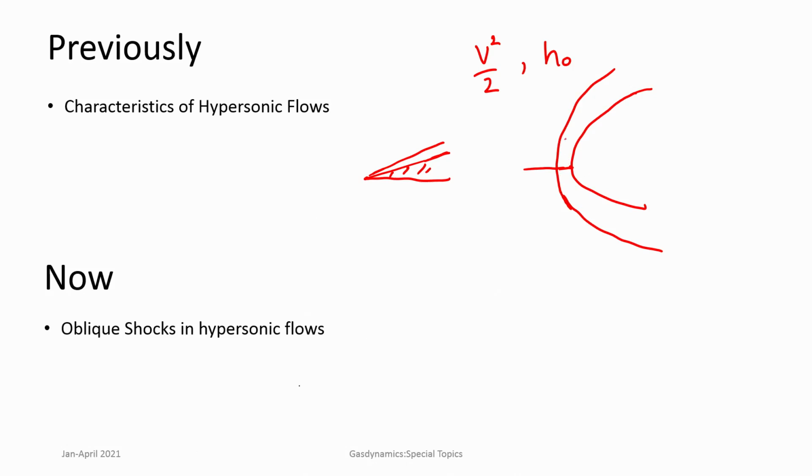It is not attached but a detached shock, and the curvature of the shock produces entropy gradients along the streamlines over here. So, from Crocco's theorem we know that entropy gradients produce vorticity, therefore you get rotational flows and they form an entropy layer, and this affects the flow over the body. So, the entropy layer can wash over the body.